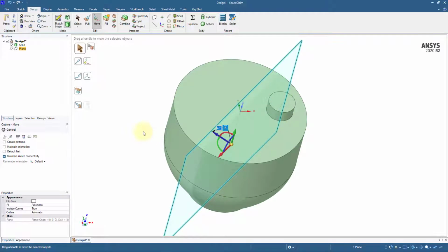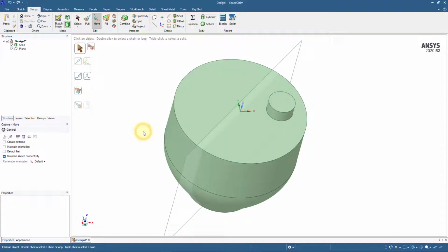For creating the helical tube, there are a couple of approaches that can be used. You can first create a circle and revolve it to create the helical tube, or you can create a helical curve first and then convert it to a helical tube. For this exercise, we'll go with the helical curve option.